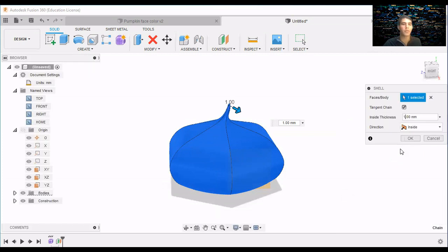So the reason the 2 millimeter thickness does not work is because it's too big. And as you can see up the top here, you can't really create a 2 millimeter thickness on this volume right here. It would overlap. So you make a smaller thickness, so geometrically you could make that shell on all the different surfaces on this object.